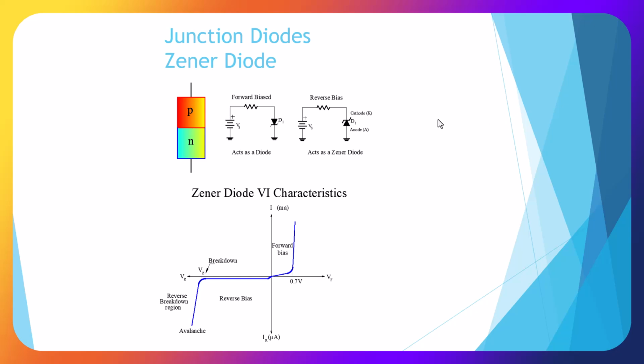So what we have here is the Zener voltage minus our supply voltage, and then we figure out our current. So here's our diagram, and we have standard forward bias, and at reverse bias, at this Zener point, our breakdown voltage, it actually will pass current, but it will be held at the Zener voltage.